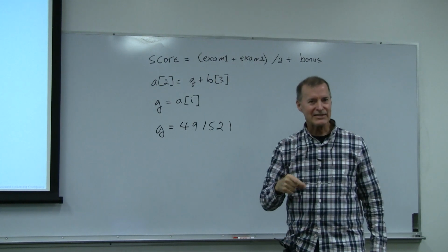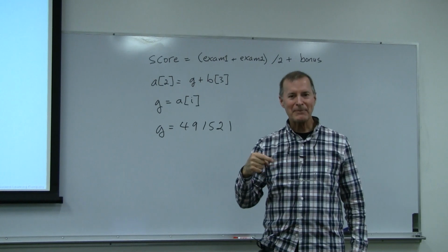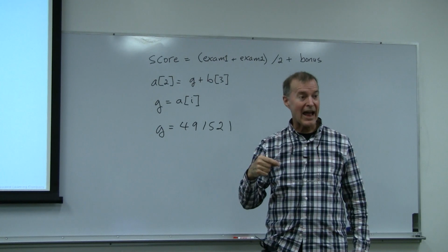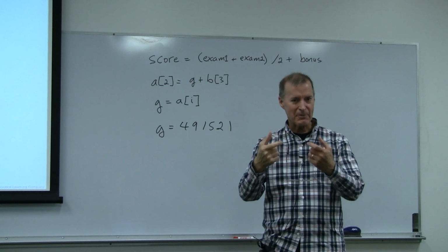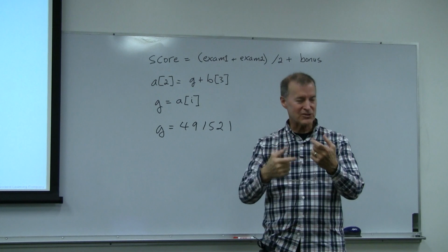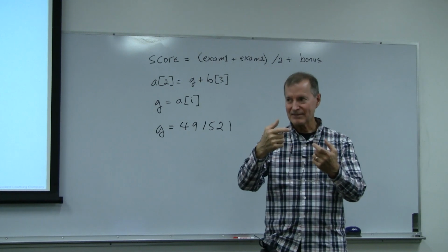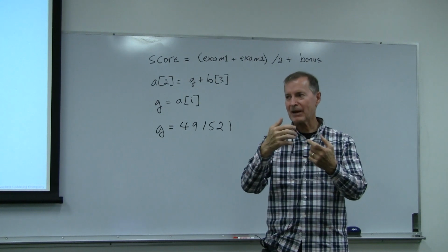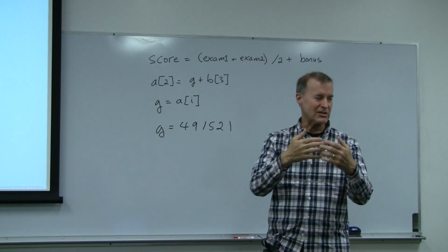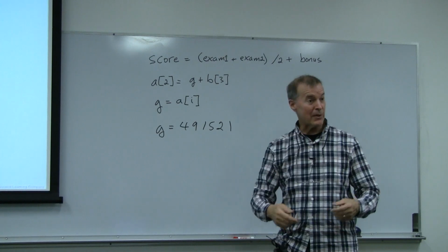So here again, in PEP 9, how did we add two 16-bit integers? Because our data paths were only 8 bits. So we had to do it least significant byte first, and then save the carry, and then the most significant byte. So it's the same, but that was at the microcode level.